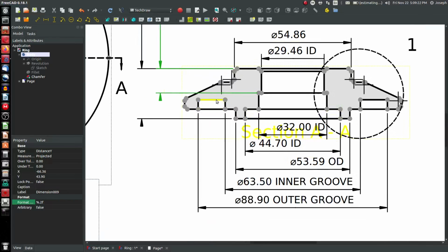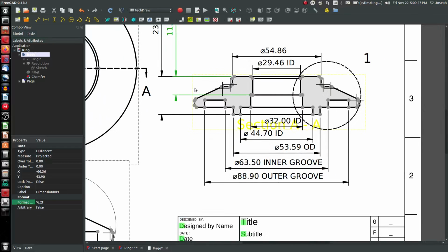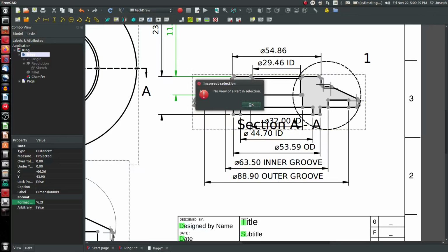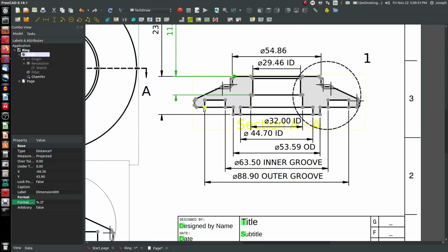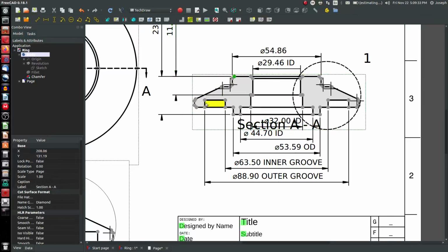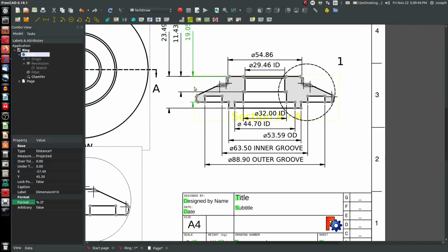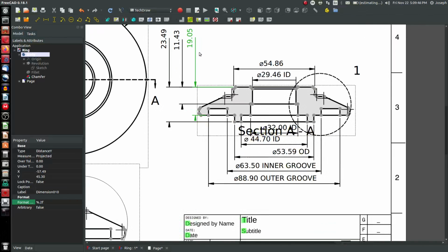You might want to locate this groove. Now it would be very hard to measure from here to here. If you want to accept tolerance stack, you certainly can add a dimension from here to here, and then dimension the groove depth off of that face. That would make it much easier to dimension in practice. But it's important to keep in mind what stacks you're willing to accept and everything at the worst case. So I can choose that, or it might be more readable to come down here, whatever you prefer.